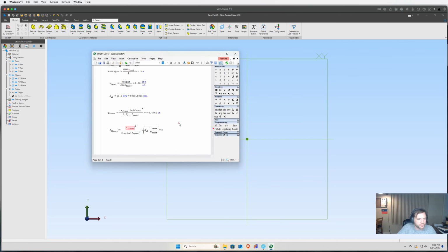And it will not compute it because we didn't tell it what lambda was, nor what M of the front was. So, excuse me. Lambda is effectively just a shape factor for determining the frequency. So that is L, lambda 1 of the front. For a clamp-free beam, that's 1.875. There are some more digits there, doesn't really matter. So we got that. Now we have to define M.